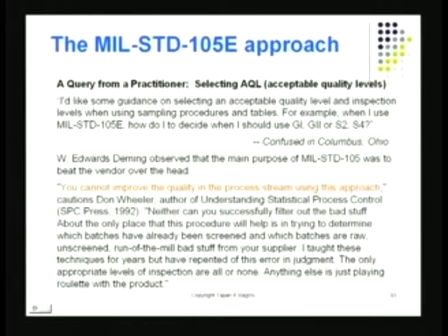Defect levels are still at percent level. We find many parts and items which are still at that level, which is like Cp or Cpk less than 1, which we'll discuss in another session. That's where 6 sigma is trying to go. But because not many people are at the 6 sigma level, people are saying we have to have some method that we can use here and now today with the kind of suppliers that we have. Our suppliers are not at 6 sigma level, so we need some method. And one such method is the MIL-STD-105E approach.